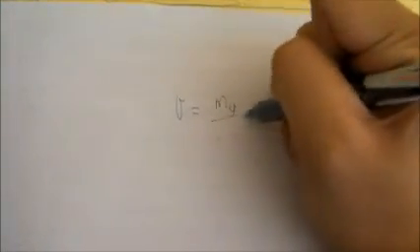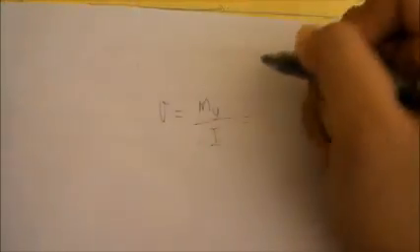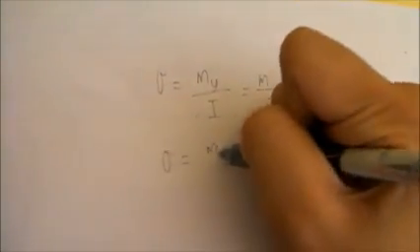The next step is applying the flexure formula. Using the flexure formula, stress equals M times Y divided by I, and equating it to the second or the special form of the flexure formula, M over S, and manipulating the first equation, we can derive that S equals I divided by Y. This is the formula for the section modulus.